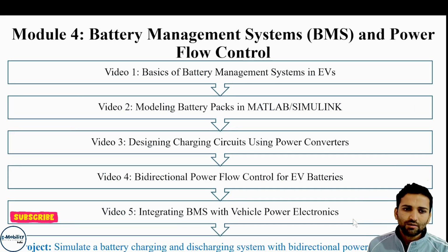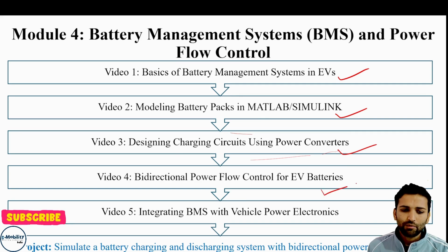Then the fourth module consists of the battery management system. So we'll be going through the battery management system basics, what is BMS, then how to model a battery pack, and then designing a charging discharging circuit, and bidirectional power flow control for the EVs. Obviously for bidirectional we'll be using that bidirectional converter, and integrating BMS with the vehicle power electronics. So again here, based on these 4 or 5 videos, we'll be doing one project. We'll be simulating a battery charging and discharging system with bidirectional power flow.